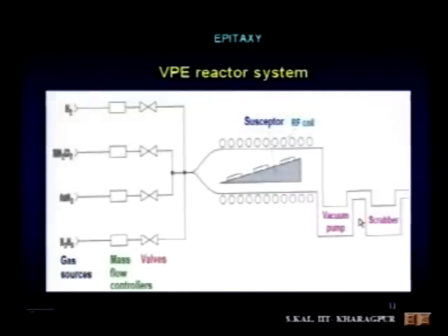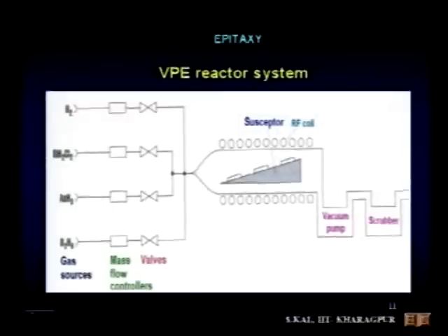So those gases are sent through a scrubber. This is the scrubber, with the vacuum pump by which you can suction those gases, and those gases are flown into a scrubber, and in the scrubber basically those gases are dissolved in liquid. There are water fountains, and as the gases flow, showers of water are thrown on the gases, and then you can dilute those byproduct gases and release them into the environment.